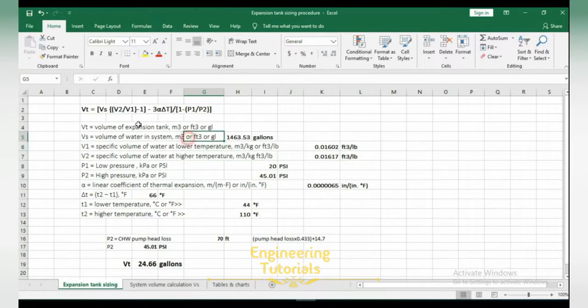So it is important to properly size your expansion tank, because a properly sized expansion tank will accommodate the expansion of system flow during the heating or cooling cycle without allowing the system to exceed the critical pressures. Also, the expansion tank basically helps maintain the system pressure by accepting and expelling the changing volume of water as it heats and cools.